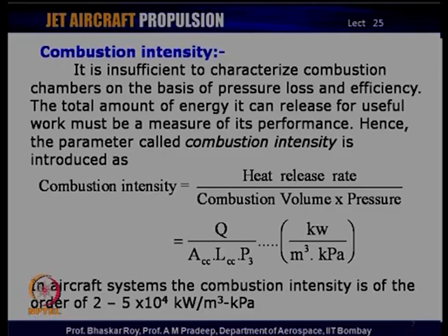So, the heat release rate is decided by a number of operating conditions and the basic chemical composition of the fuel. And then we have the combustion volume, which is decided by the engine designer. So, in case of an aircraft engine, the volume available would invariably be very low, and as a result of which you need to have very high combustion intensity.